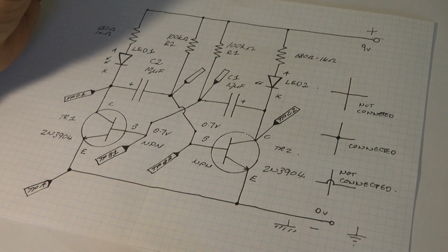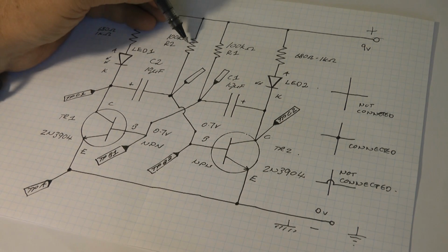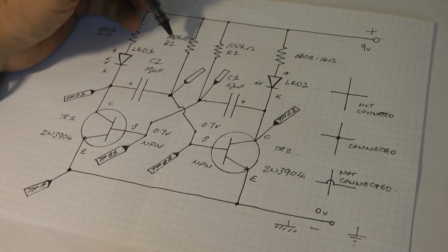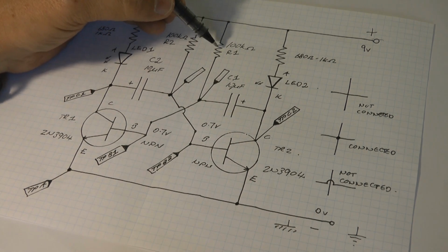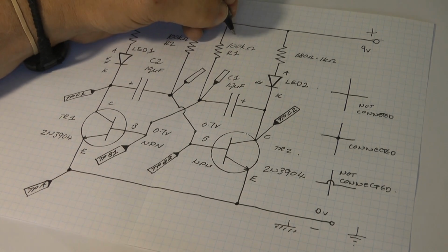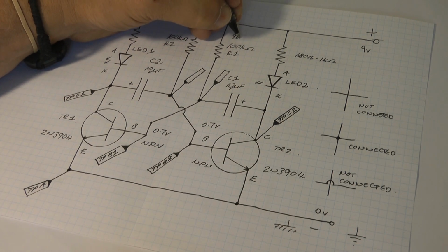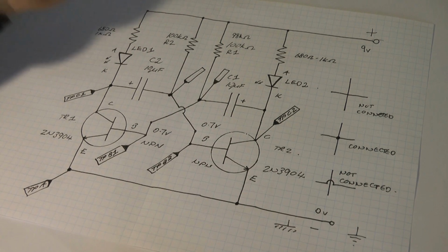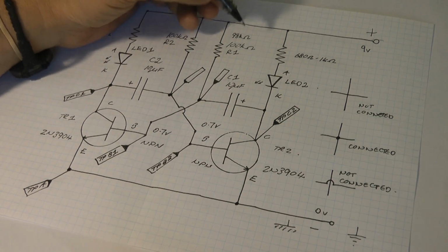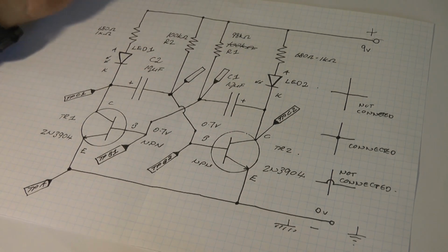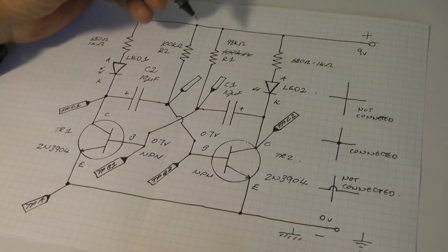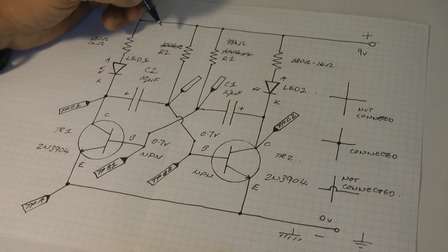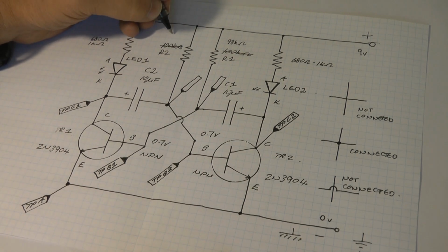Now it's reasonably safe to assume that these resistors, even though they are nominally 100 kilo ohms, maybe this one is, let's say, 98 kilo ohms in terms of its 1% or 5% tolerance on the part, so it's not quite 100 kilo ohms. And then this one over here is maybe, I don't know, a little bit more.